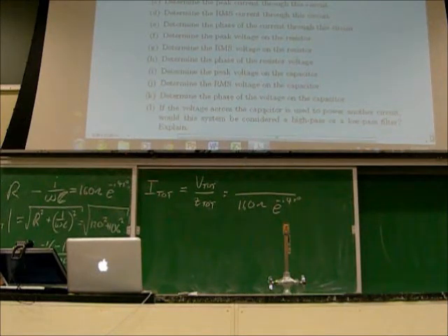I've heard some people say peak, I've heard some people say RMS. I have not found the answer to that question that I'm looking for. Am I using all RMS values or all peak values? Doesn't matter. I heard the answer, yes. Okay, the answer is yes. This formula is either all RMS or all peak, but don't mix them.